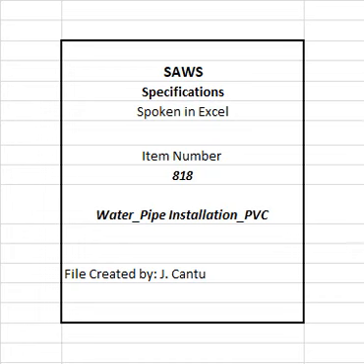A. Submit shop drawings showing design of new pipe and fittings indicating alignment and grade, laying dimensions, fabrication, fittings, flanges, and special details. B. Contractor to review and submit PVC pipe manufacturer's recommended installation procedures. C. Calculations and limits of thrust restraint shall be based on AWWA M23, latest edition.